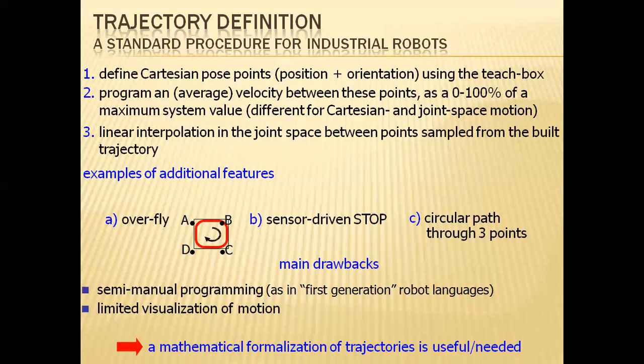So for that convenience, only the work parts will be transferred, but the sequence of process may differ depending upon the design criteria. First milling has to be performed, later drilling, or later the reaming process. So for our convenience, we transfer by bypassing one process as per the requirement.